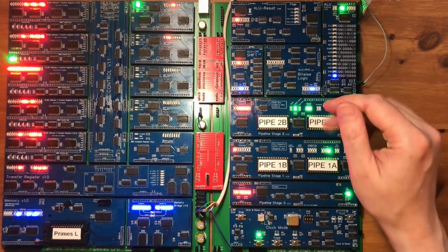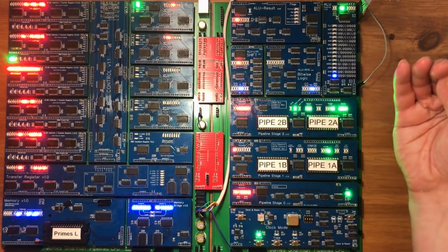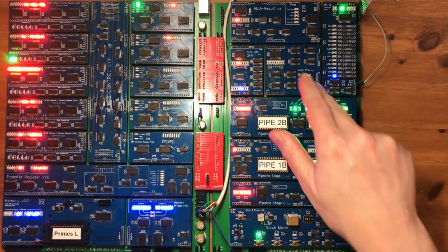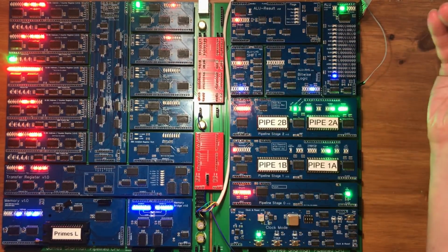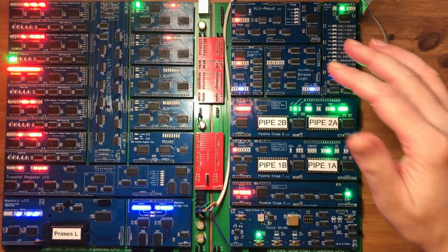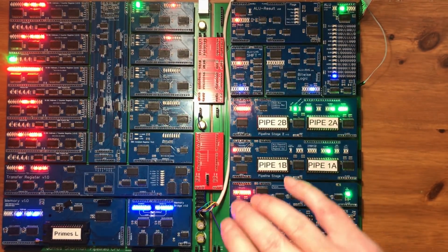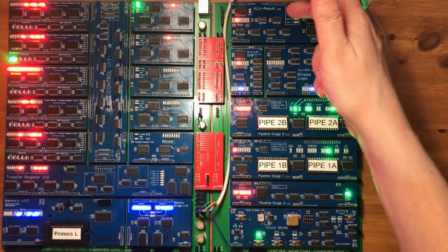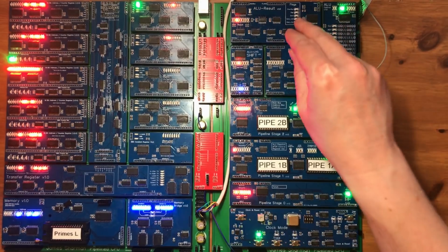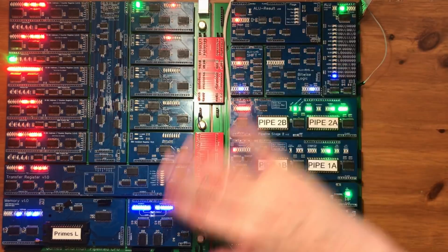We can't allow that. So what we would need to be able to do is have a method for saving and restoring the flags. And the way you do that is you have an additional register, so the flags aren't used directly. Whenever we change the flags, we latch the value of the flags into that register, and the output of that register is actually going to be what the rest of the processor sees. And then we connect that register to the main bus so we can perform a save and restore on that register contents, either through one of the GPRs or maybe a push F, pop F instruction pair, something like that.